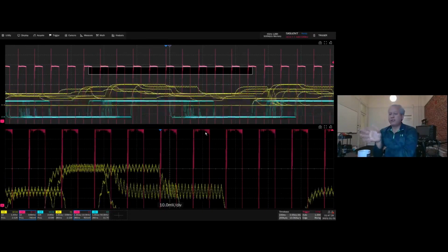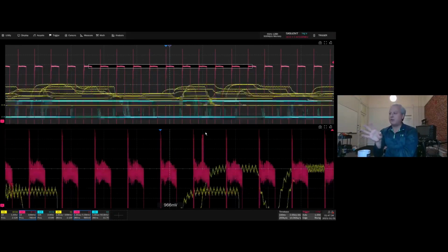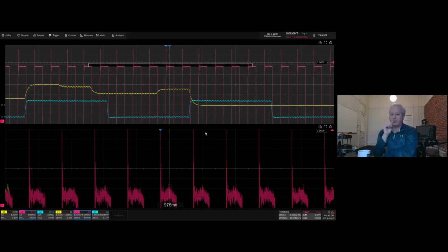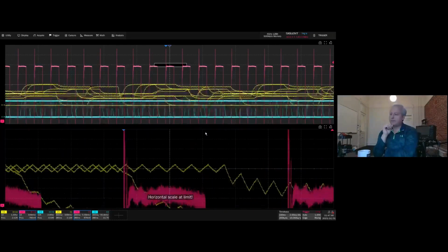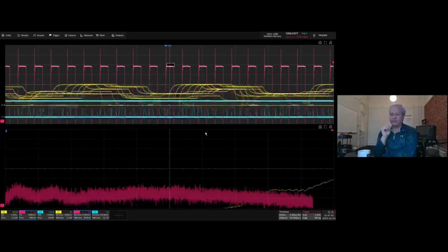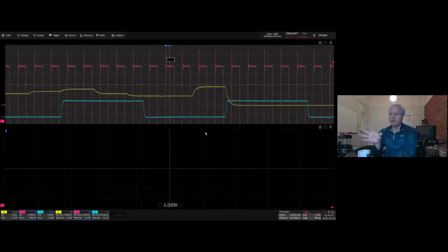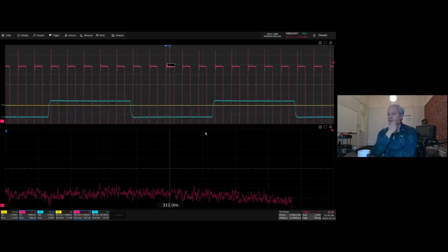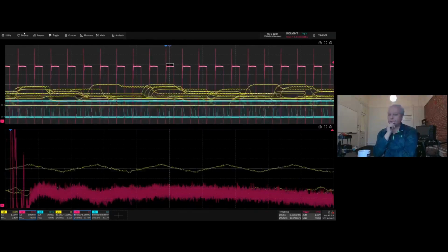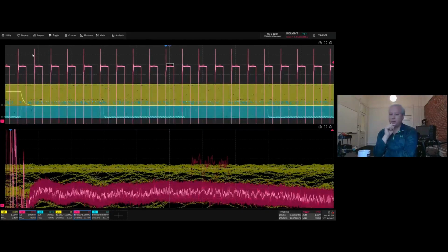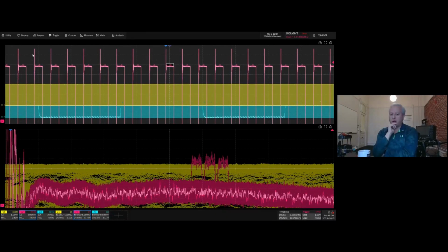Now we can use persistence, once we isolate that top of that wave there, we're going to spread out a little bit further. There we go. Now we're zoomed in good. So now we can switch to the persistence mode to isolate an infrequent pulse event here. There we go. So there we see that pulse that's happening within our signal.